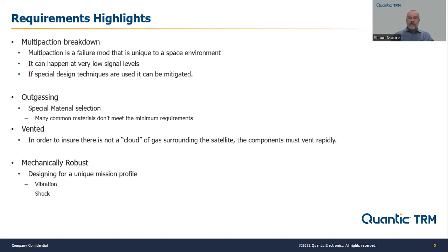These are things I think are very important for any satellite integrator, whether they're going to a LEO orbit for a very low-cost satellite or not. I think multipaction mitigation is something that really needs to be done. Now, whether or not you test for multipaction is a whole other thing. The test is typically quite expensive. But if we can at least do the analysis to say that we've mitigated it, that's usually all that these lower-cost Space 2.0 customers are really concerned with.